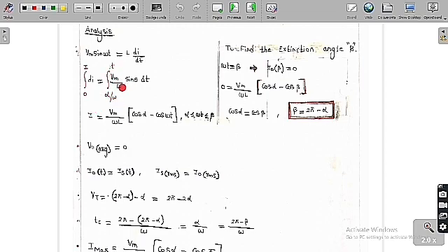A very important point: from alpha by omega only, the current is 0 at that position. So from time alpha by omega, at which the current is 0, it again becomes current I at time t. Therefore here we have to integrate from alpha by omega to t, and the current from 0 to I, because from alpha by omega only we are going to get a current of 0 value. Again, up to t, the current expression is I of t.